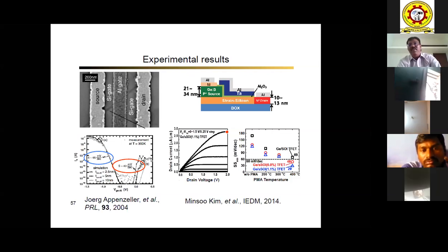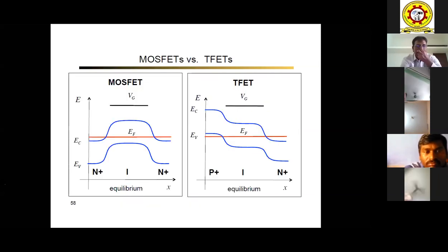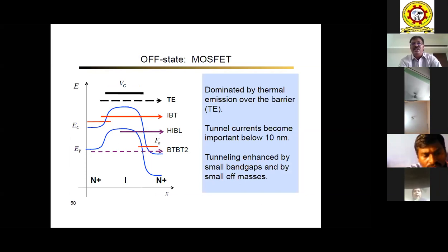And if I reduce the voltage level at the gate, then again there is a gap between these levels. That can be actually shown here. So by applying the gate voltage, we bring this band closer so that the carrier can tunnel band to band. So that's how the movement is. It's no more like your conventional energy band diagram. It's actually tunneling band to band by controlling the gate voltage. That is the logic behind tunneling field effect transistors. And they are quite promising candidates at the moment.